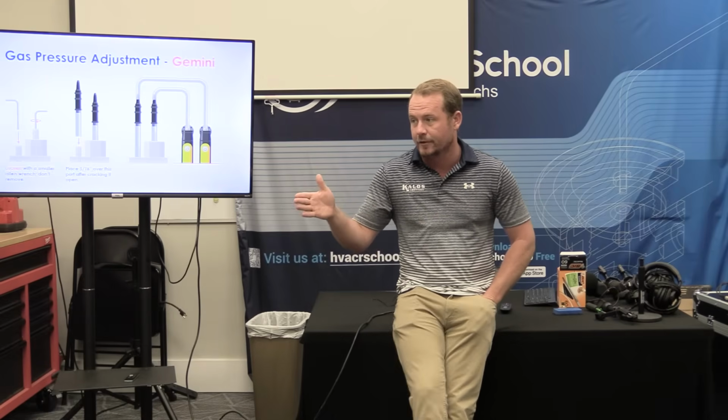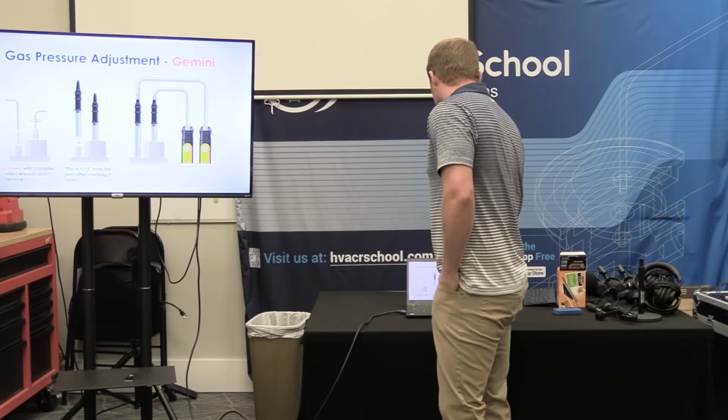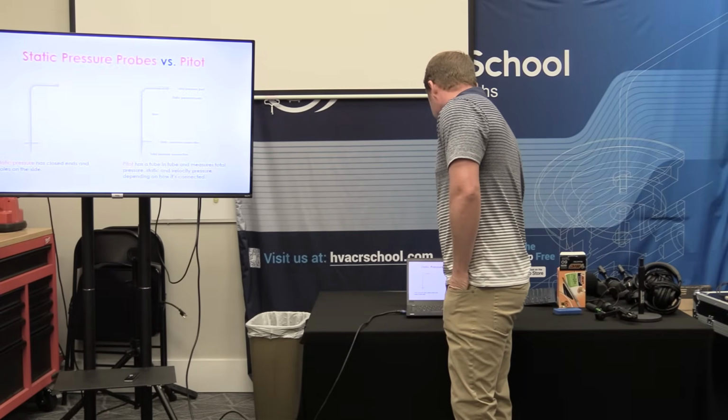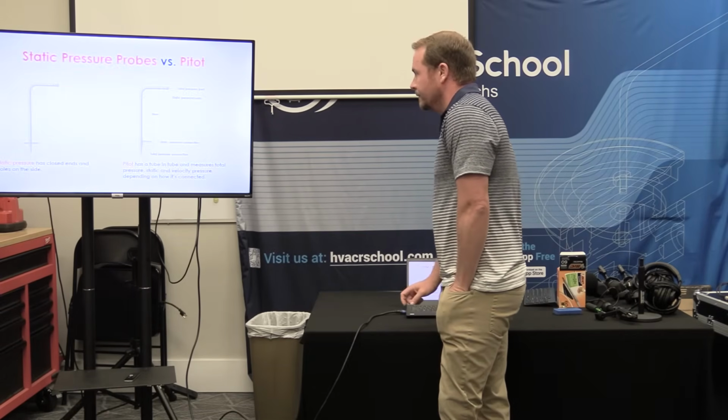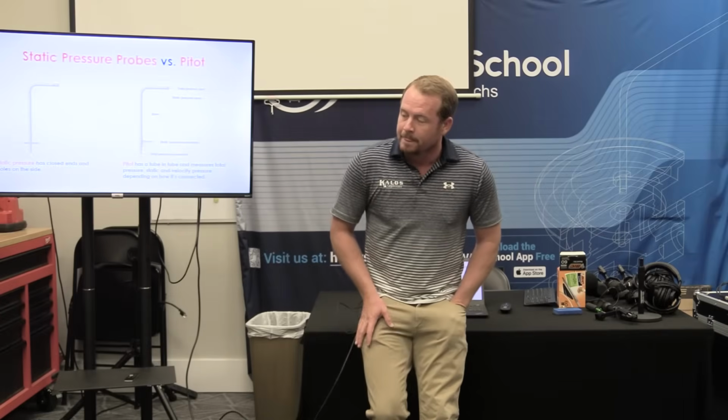Okay, I know that was a lot. Is there any other way you would like to say that, Bert? I know I just spouted a lot of information. Go to check static pressure, just zero it out right there. Right. Don't rely on yesterday's zero. Correct. That's the main point.